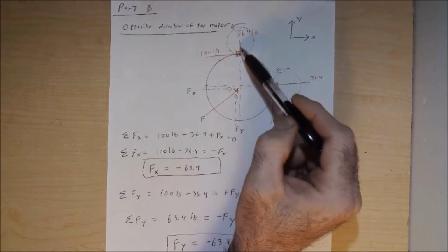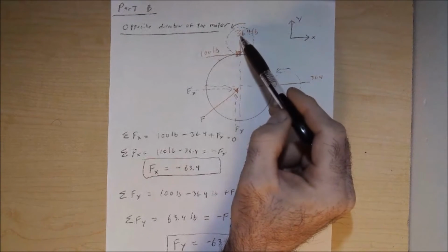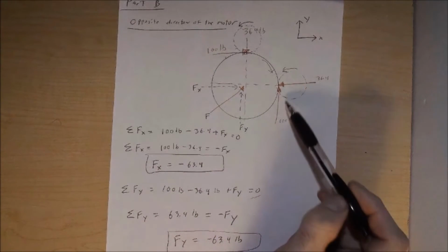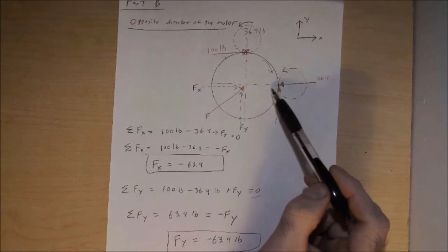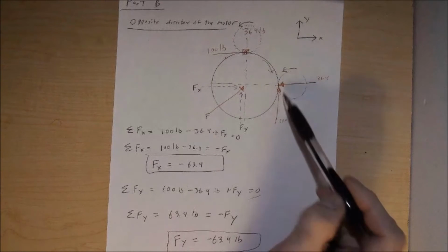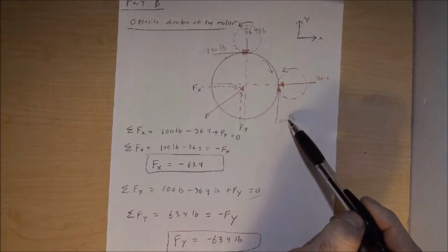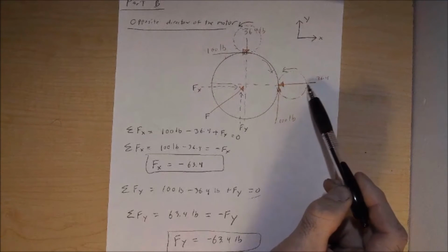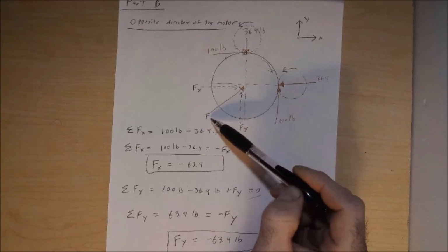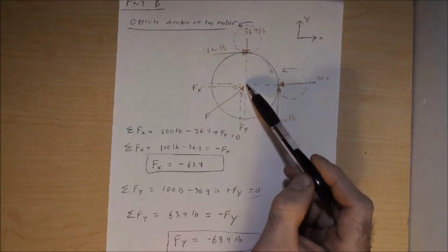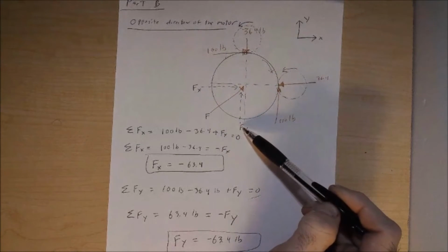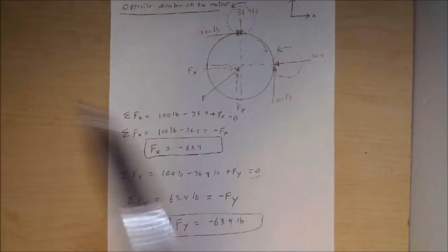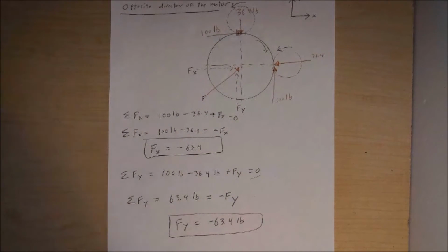Our radial load F sub r here is still going down our negative y of 36.4 degrees here. And then over here we can see that now this load, F sub t, in between our idler and our machine gear here, is going up in the positive y direction as well. And our radial load is coming in here in a negative x direction like that. Where we have our support load over here, F, at the shaft of our idler, still has a positive Fy and a positive Fx. So now we can go down through and again do out for this free body diagram